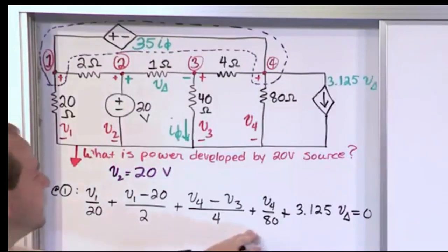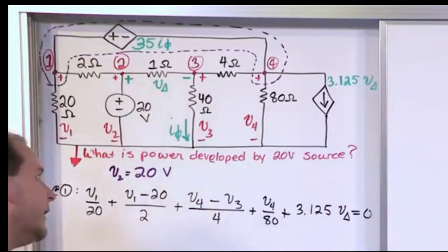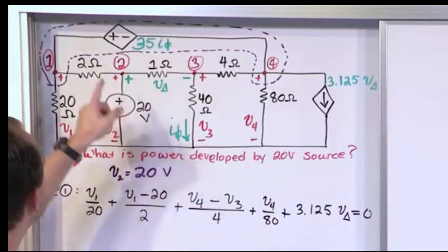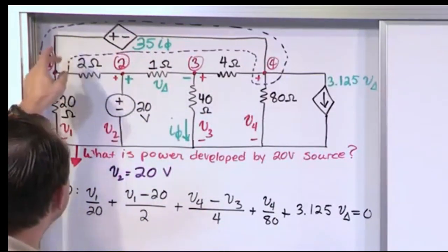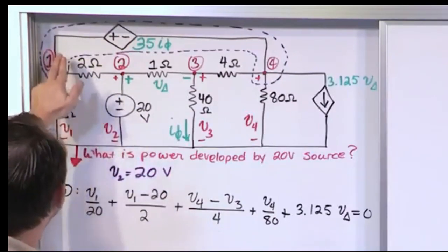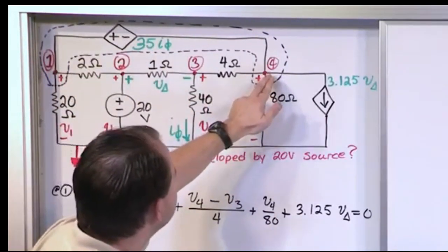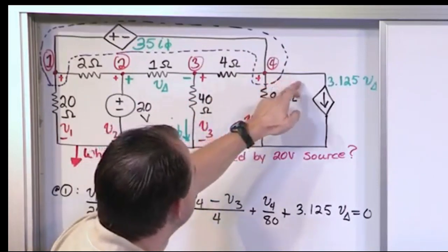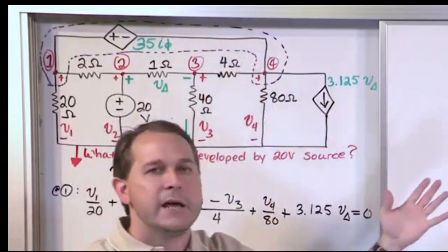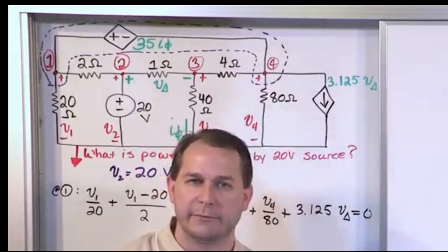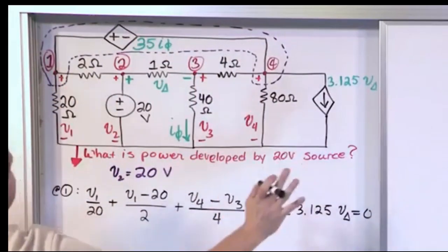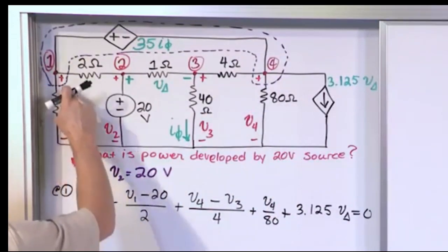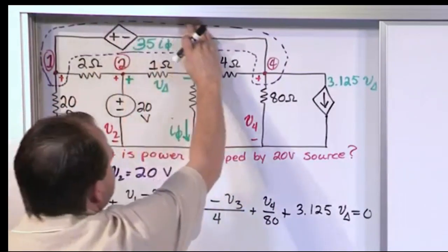This is a node voltage equation. It is a shortcut because the only other way to get it is to pretend there's current flowing. Well, there is current flowing through there, but to make up a new variable, I would have this stuff plus I over here. When I got to this side, I'd have this, and I'd have minus I coming in. Then I'd add those two equations together and I would get an answer. Instead of doing that, I just pretend it's one giant node, eliminate the intermediate step, and say this is a current, this is a current. Okay, this is all connected as a supernode.